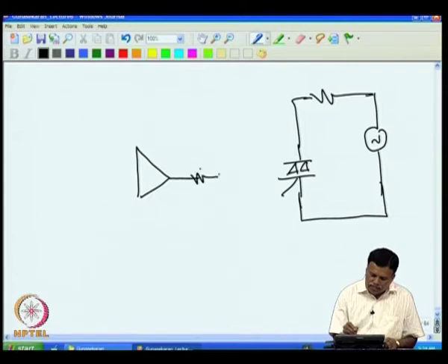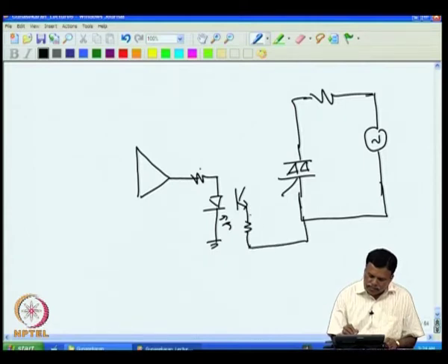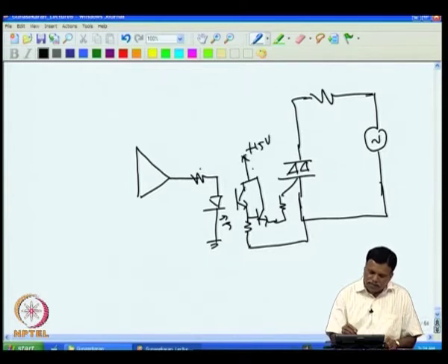Now, instead of giving directly to this, I can connect to the opto isolator's LED, that can be connected to the other side, which we had done earlier. And that is the plus 15 volt, whose ground is this, not the ground of this. So, you have an isolated plus 15 volt, that will drive the opto isolator. That way the isolation is provided.